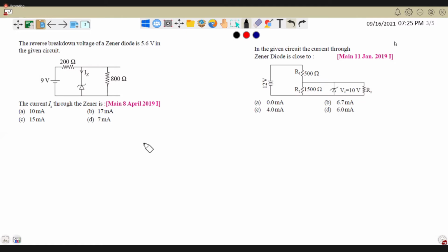No? Okay, see. This is a 9-volt battery and this is 5.6 volts, right? The Zener diode works in reverse bias. That's okay, let us put that aside. See, this is 9 volt, hence this is 9. When it comes to here, it is 5.6, correct? At this point 5.6, this is 0. Hence, this is 5.6 and this is 0, right?